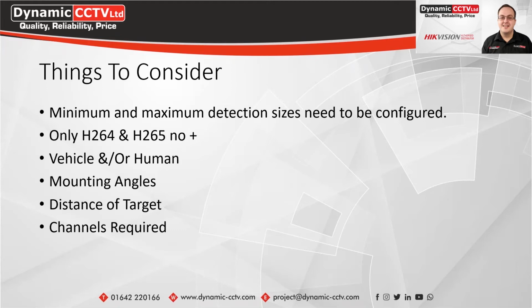And you also need to make sure that you've got enough channels of the alarm filtering to cover the site that you need to be covered on the actual system itself. So it is always worth checking those depending on which of the NVRs you go for. And there is also the super NVRs, which have more channels that you can enable the alarm filtering on as well, which you can always discuss with us depending on the scenario.